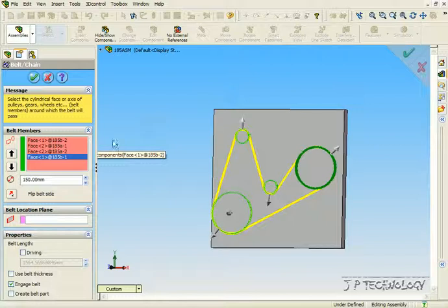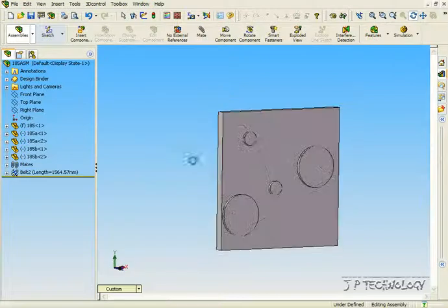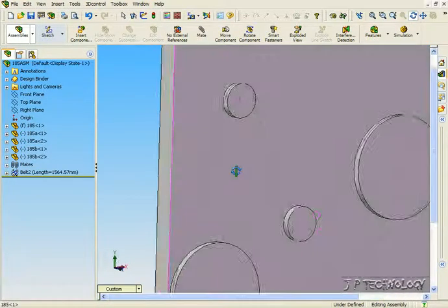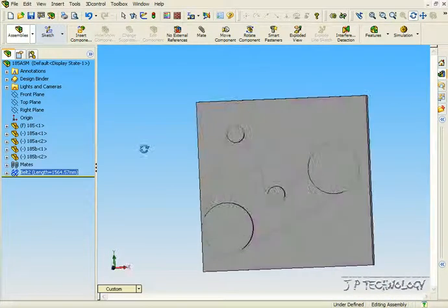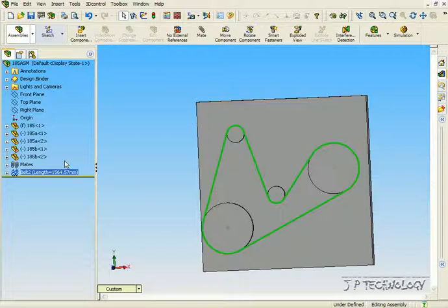So for this one, we've got our belt and chain that we like. It looks good, fits everything how we want it. Let's click OK. And now we have our sketch for it. So now all you have to do is from this sketch, extrude it out and make whatever it is your belt is, like how thick you want it. If you want teeth, if you don't want any teeth, it's up to you.